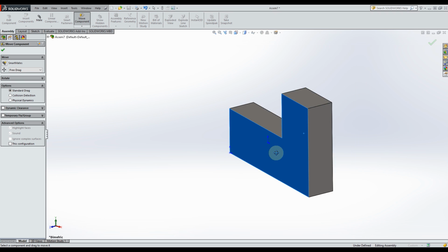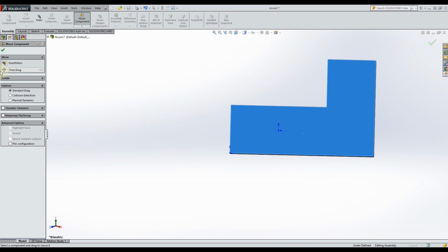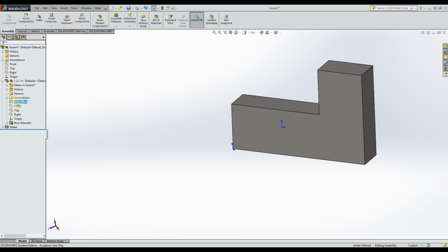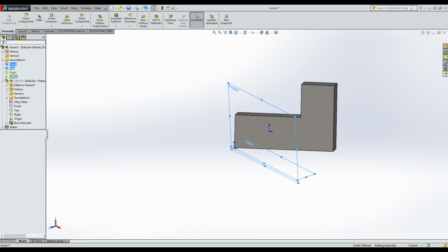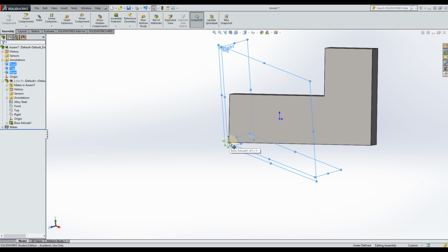Once we've done that, you can still rotate the part around, which is always what happens when mating with points. So what we're going to do now is make use of the extra planes. We have the assembly planes, and what you will notice is the only point crossing all 3 planes is the actual origin. Meaning that if I would mate all 3 planes to the 3 planes of my main part, it would also be fully defined.